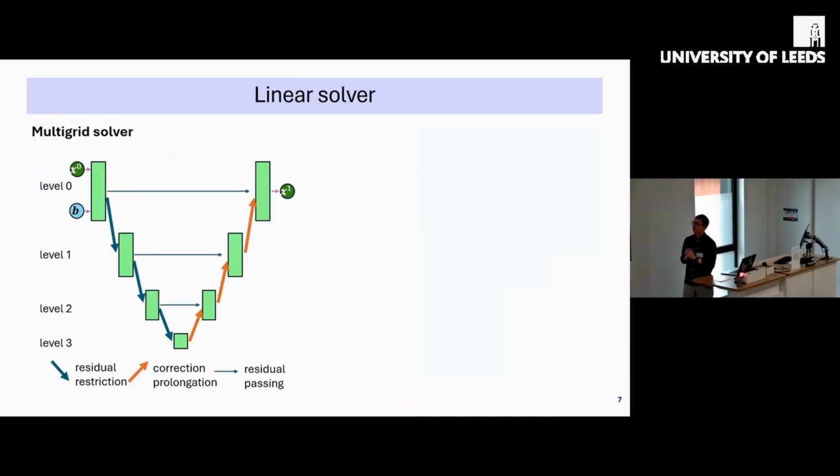Okay. So in the multigrid solver, you start with the fine mesh in your problem. That's the discretization we saw before. That's the Ax equals b, and you can use an iterative solver to solve that, like a plain Jacobi iterative solver, or GMRES. But it usually wouldn't be very efficient because you have different frequencies of errors, and your iterative solver usually only tackles a part of the frequencies.